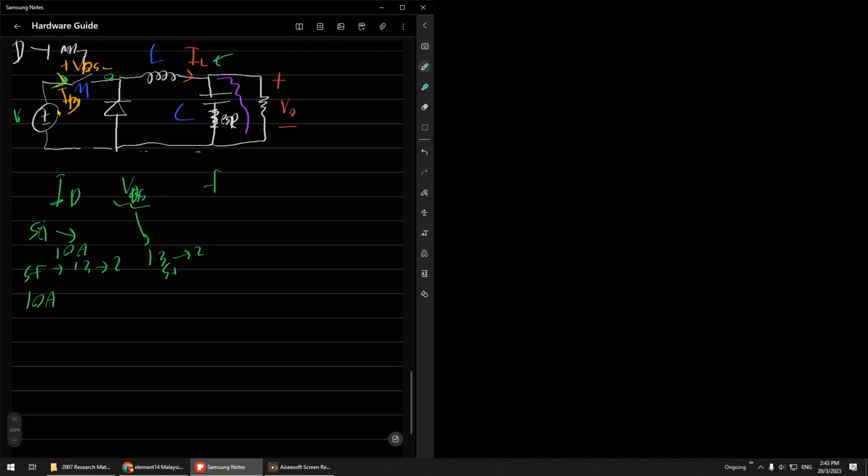If you use flyback, for example, V in is 100, so VGS needs to make sure it can withstand 200. It will become double. So that's why I suggest in simulation you have to measure, because some topology can make the voltage double. So for example here, if the voltage here is 50, I suggest 100 volt. Okay, that is the rating.